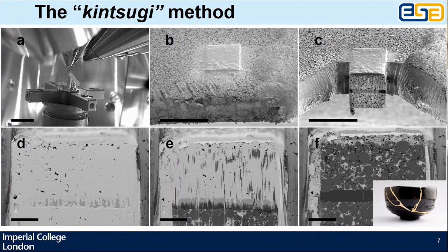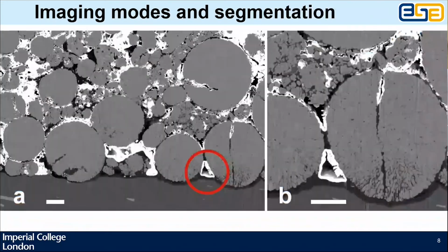And what you're left with, once you do a very fine polish, is that all of the back walls of pores are now coated with platinum and show a very strong contrast, whether it's in backscattered or secondary electrons. The image is somewhat reminiscent of the Japanese art of kintsugi, which means golden joinery, a way of repairing broken ceramics with precious metal amalgams. And so that's one way to improve the contrast in these images and make phase identification easier.